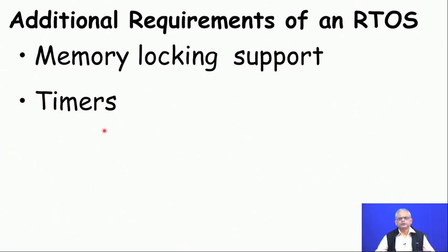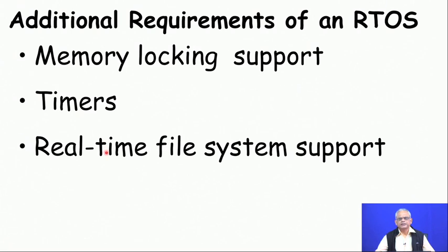Support for timers, both periodic timers and one shot timers, high precision timers. These are frequently required in writing real time applications and need to be supported by the operating system. Real time file system support. In the traditional file system, the blocks are written based on where space is available on the disk, but then the access time of the blocks varies depending on where it is located on the disk. In a real time file system, the blocks are written consecutively, so that the access time to the blocks becomes predictable.